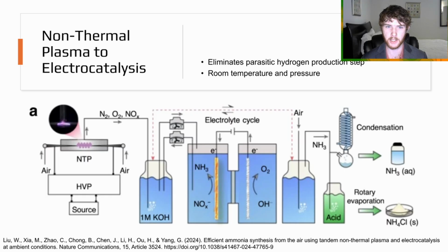The lab system is able to give a dual purpose to the potassium hydroxide solution they're using to dissolve the nitrate compounds. This would essentially need to become a distillation column, but instead of having simply one chemical being fractionated off, they would need to essentially have the lower half be absorbing the NOx compounds and the upper half stripping the ammonia compounds. There's going to be some complexities in doing that, but I think it's fairly achievable.